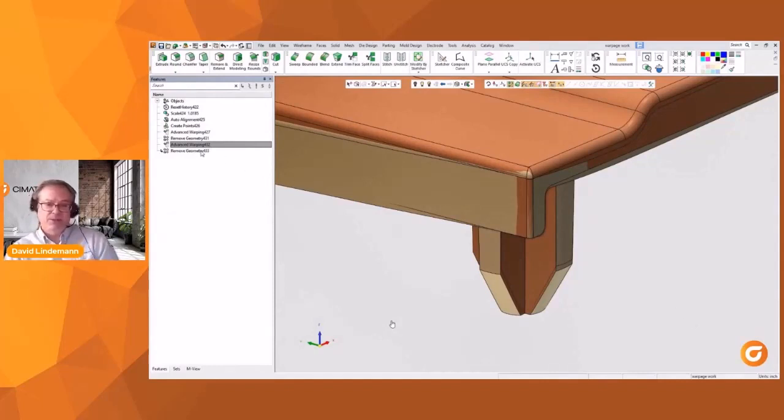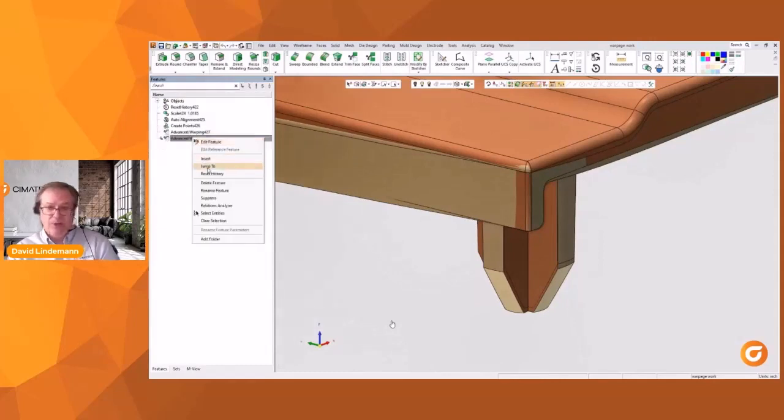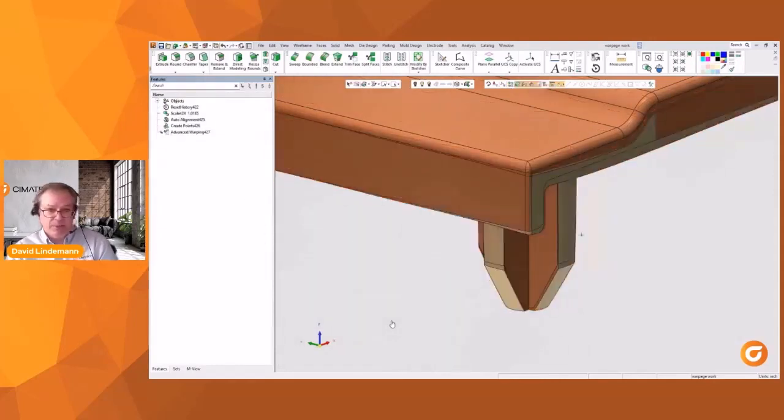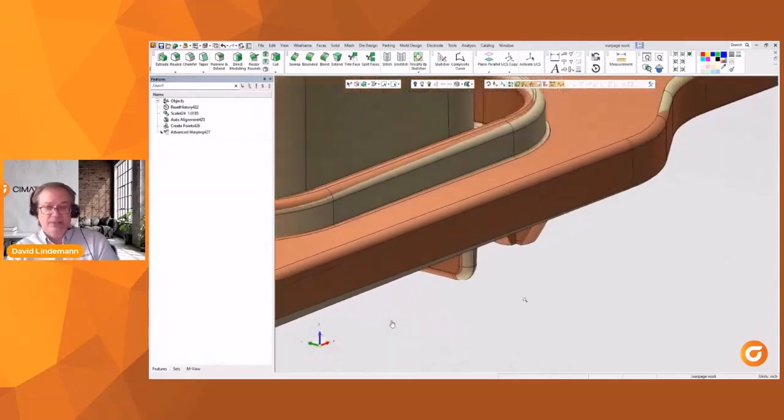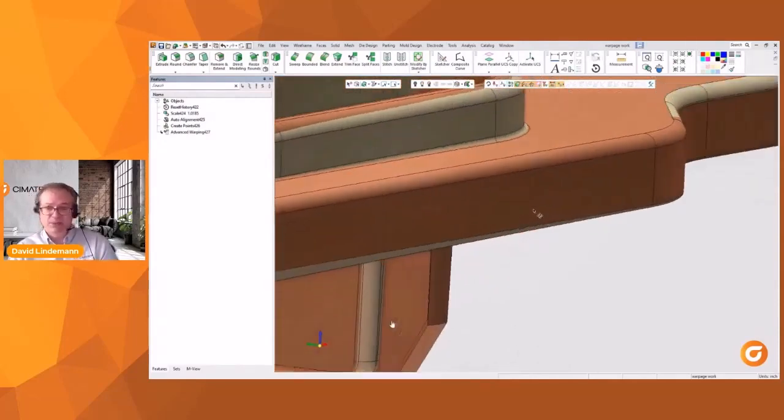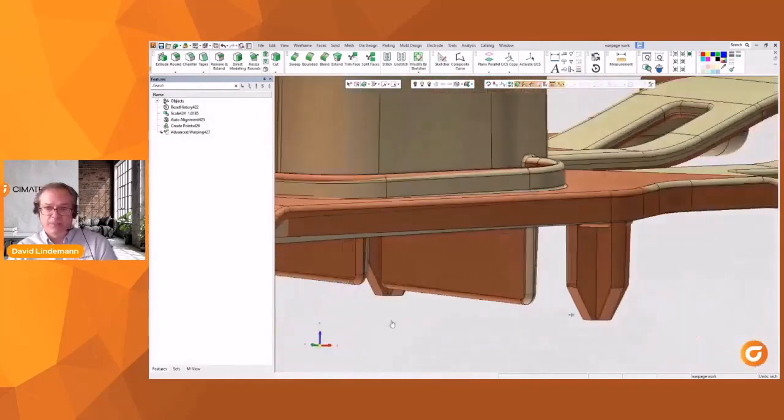So that's something that's just there in the software. If you have a simple change, it's pretty straightforward to just snap a part out like that, and you'll see it bow. Like maybe the part on one side bows in, so you have to compensate. Say it bows in 1.5 millimeters, you have to compensate by bowing it out 1.5 millimeters. That is very possible with this one click, this one function.